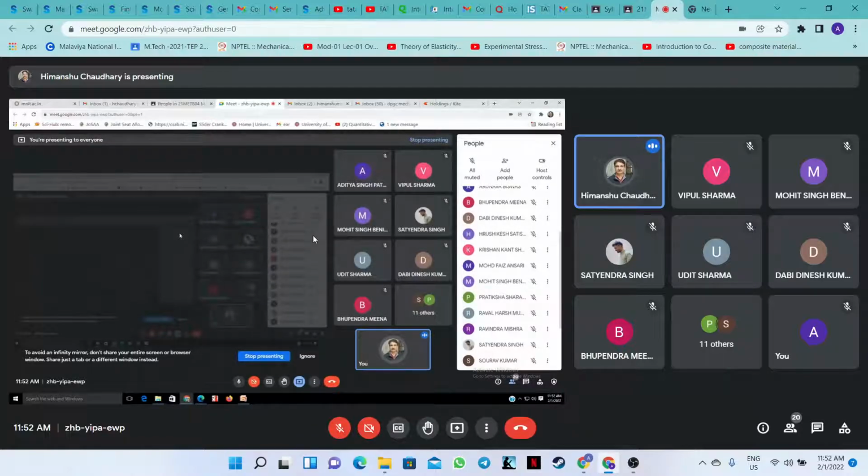Same way, 3 for the crank and 3 for the piston. If they are not connected, these 3 bodies are moving independently. Is it correct? Yes, sir. So there are 9 parameters if there is no connection. But what we do is connect them by a revolute joint. So by joining with a revolute joint, they remove some degrees of freedom. After introducing a joint between links, will the degree of freedom or number of independent parameters increase or decrease? Sir, decrease. Decrease, because they will make a connectivity, some constraints.